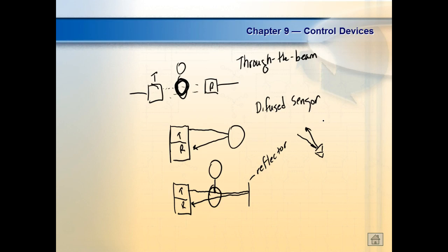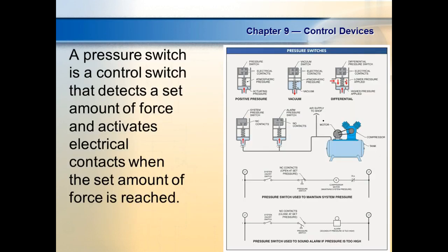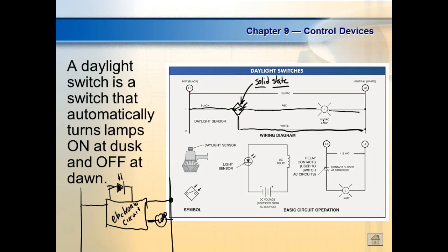One is going to be the signal wire and the power wire coming from what? From L1, and then you got to make a direct connection to L2. So these solid state sensors, most of them are going to have to be powered up, right? We do have what they call a solid state limit switch that powers up through the load. So it draws very little current. It does drop a voltage, but it doesn't drop enough to affect the operation of the circuit.